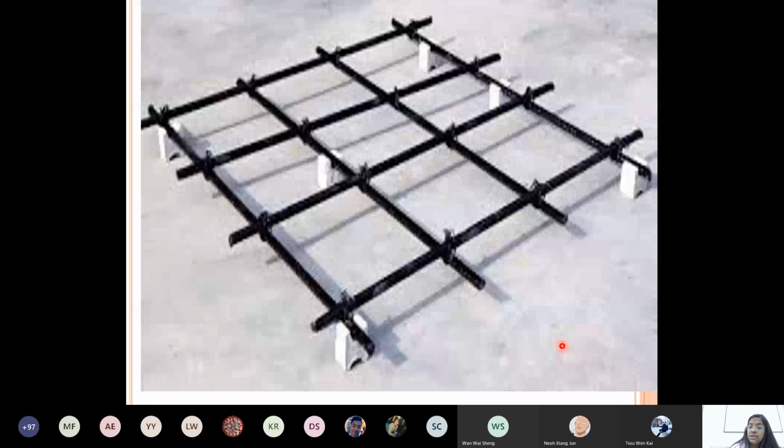Covers, these are all called covers, to have complete finishing and to avoid these reinforcement protruding out or seen out of the concrete or exposed to outside air and water or any other type of environmental changes, to avoid these types of materials subjected to changes, degrading quality and spoiling later on. You should completely check for the cover and then go for concreting.